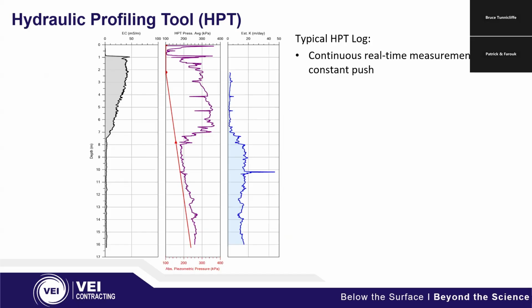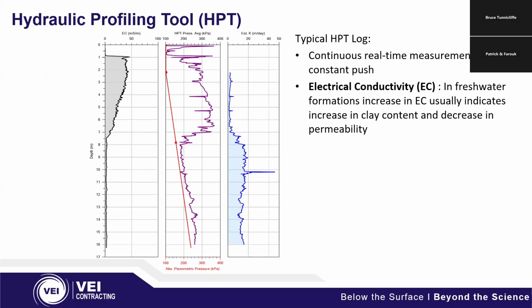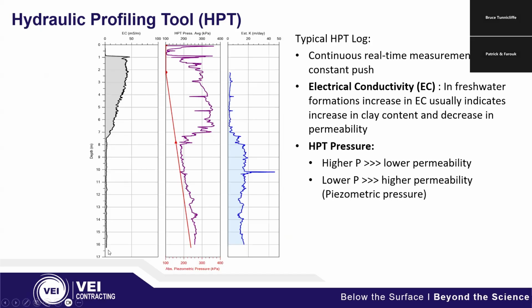So again, continuous real-time measurements and a constant push. The only time we really stop to push is to put a new rod on, and then we just keep trucking along, going down in the ground. And as I mentioned before, we have that increasing clay content up near the surface for this particular log, and then down below we have this nice sandy aquifer.